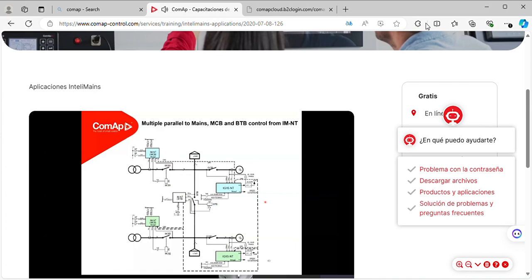The second one is multiple utility system, multiple genset group, and in between there is a bus tie. So this bus tie breaker cannot synchronize the utility system, but this can synchronize your genset 1 with genset 2, because it is again sharing information over the CAN bus, and it is also measuring the bus left voltage and bus right voltage. And once the voltages and frequencies are not matching, it can send a request to the genset on the left bus or the right bank to regulate the voltage and frequency. And once the phase is in close proximity, it can close the bus tie breaker. So it has sync check protection and other voltage balance and current balance protections on the bus.